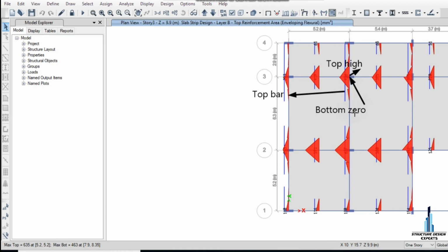and the top rebar on both of these sides is needed. It must be provided to minimize the shear force here. And this is the column. It also provided the top rebars for all the columns, and here in the mid span there are no top rebars provided from